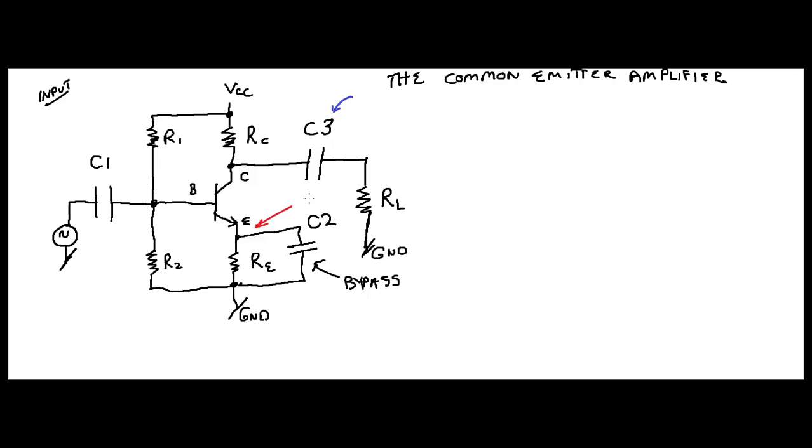Now, in the last section, we just finished stating that for an AC signal, as long as you have the right frequency range, it's seen as a short. So if you have a signal coming through here, let me just draw that in red, okay? So if we have a voltage signal coming through here like this, right? This is your voltage in, V in, okay? Now it's great, the frequency is in the right range for the capacitance to be seen as a short.